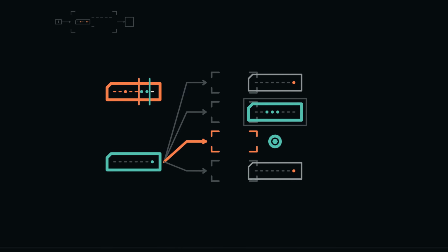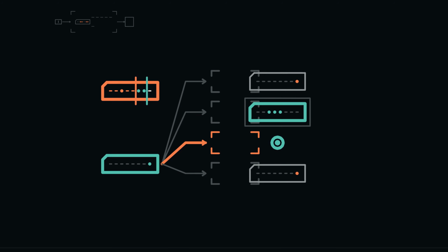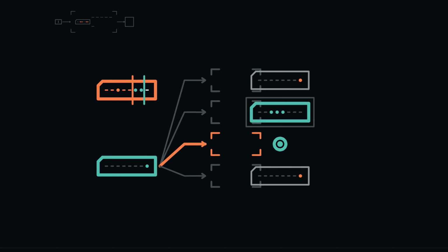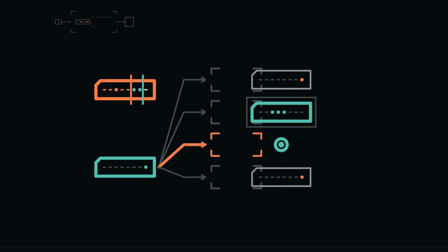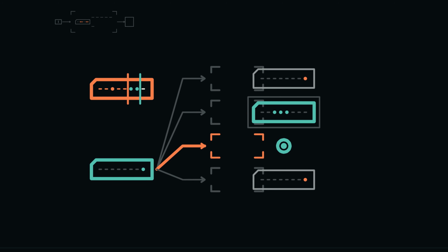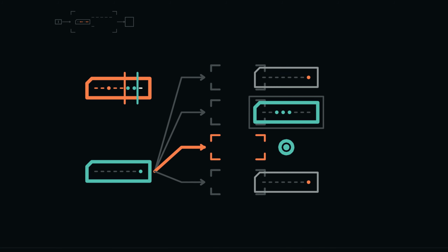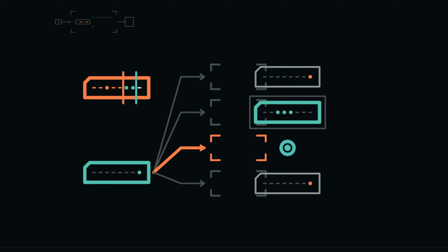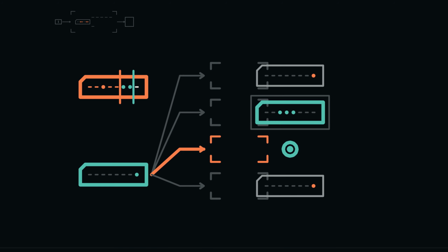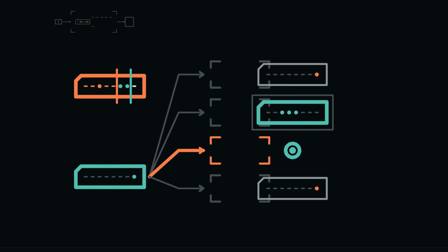Try hexadecimal 26 followed by 01. Opcode 4 selects move. Field A is 11, selecting destination R3. I must be 0. B's low 2 bits select source R1, and its upper bits are all 0. The promised transition is R3 receives the current byte from R1. Flags are preserved. State what would make the encoding illegal. I equal to 1, any non-zero reserved upper bit in B, or an unassigned opcode. A decoder must reject those patterns before execution invents an unofficial meaning.